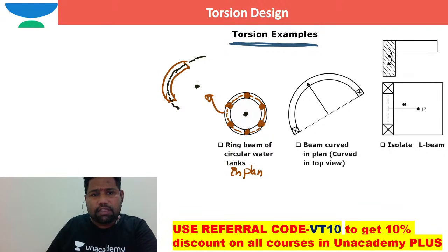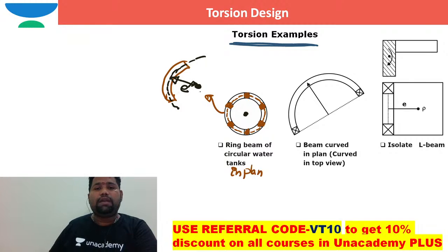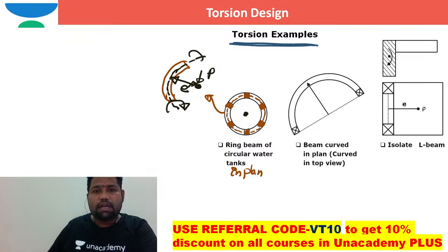If I take this load at this point, there is some gap between the shear center and the point where the total load has been applied. This is the eccentricity. Because of this eccentricity, definitely about this axis some torsional moment has developed, because this is in plan.